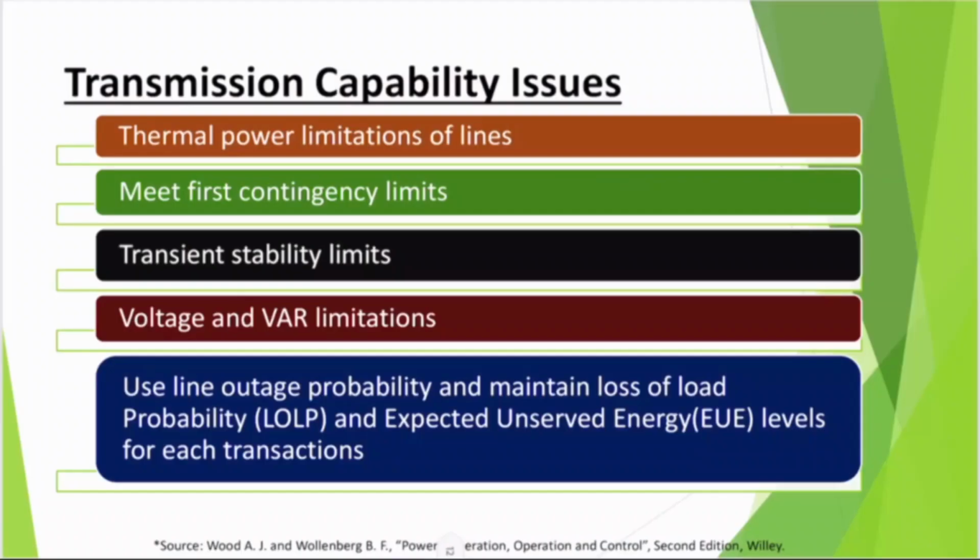We cannot shut the system because one corridor fails. We have to accommodate it through the rest of the lines by diverting those energies. So if your system is satisfying n-1 contingencies, then your capability will reduce further, because you are keeping a spare capacity to carry excess energy during failure of some of the facilities.